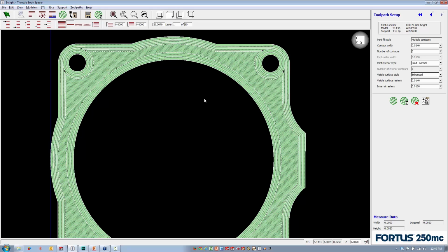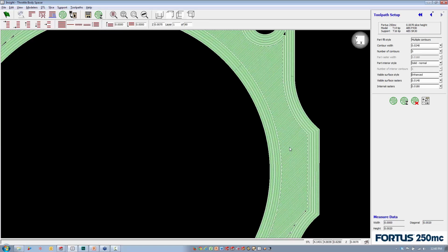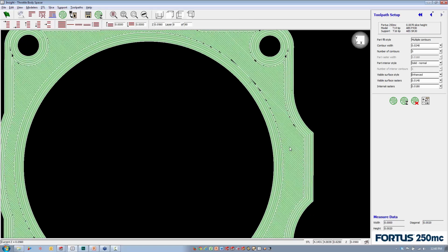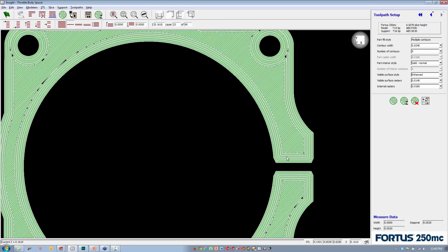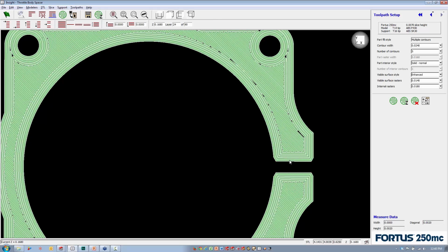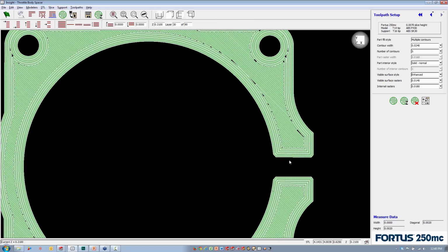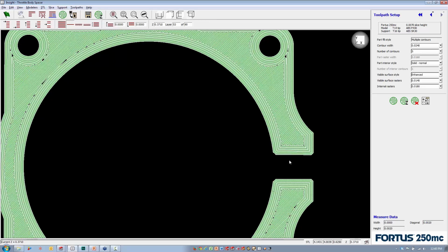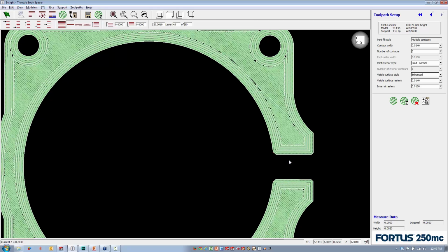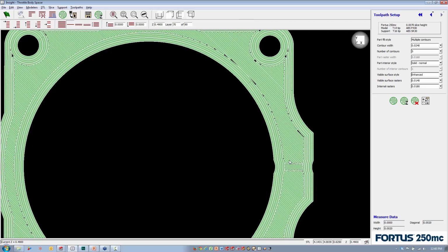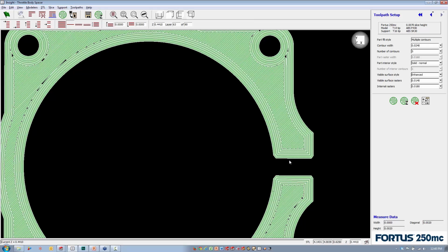Also, as I scroll up and we start to reach the through hole that's threaded, notice the skin is also thicker on the through hole, which I ended up threading. By making it thicker there, it gave me more meat to thread into, so my thread's actually going to be stronger. Even if I didn't have to worry about pressure, if I was just going to do a threaded hole, this is something I'd want to do as well, because we don't want to be threading into the rasters, because that's where we get the voids, like you see up here in the top left corner.